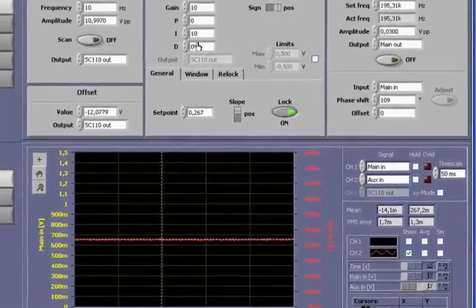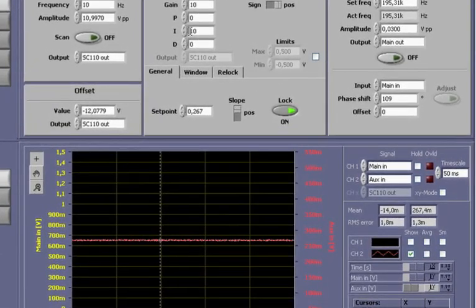For that, I will place the cursor before the highest digit in the field of the I value. I press the arrow up key and increase the value. You will notice that the cursor remains in front of the highest digit, even if I cross from 9 to 10 or from 90 to 100. This allows me to quickly scale the parameters and determine the order of magnitude.